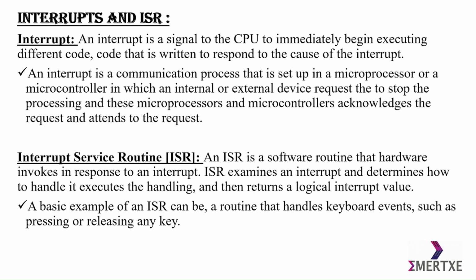An interrupt service routine is a software routine that hardware invokes in response to an interrupt. The ISR examines an interrupt, determines how to handle it, executes the handling, and then returns a logic interrupt value. A basic example of an ISR can be a routine that handles keyboard events such as pressing or releasing any key.